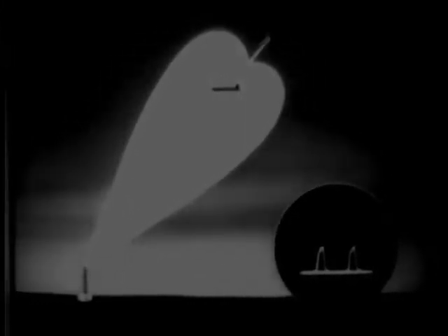To sum up this business on lobes, take a look at this miniature of a pip matching radar. It has two horizontal lobes, like this, for measuring azimuth, and two vertical lobes for measuring elevation. Together, the four lobes make it possible for the radar beam to be centered on the target all the time, thus assuring you of highly accurate data. And of course, for each pair of lobes, there is a separate scope picture, one for measuring azimuth, one for measuring elevation. This type of pip matching presentation is called the K-scope.